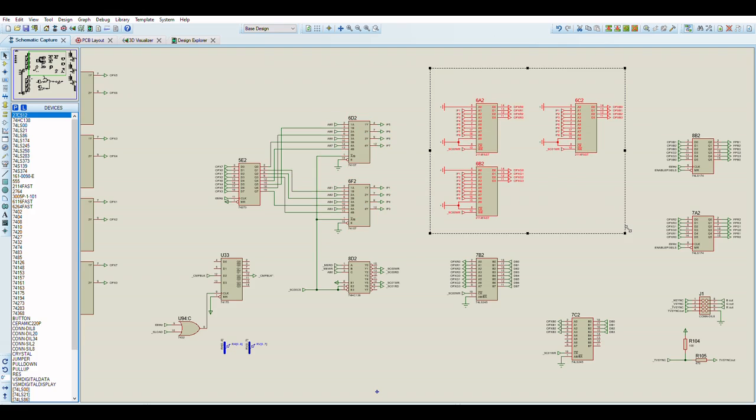These are 4-bit outputs, and there are 3 2114s, and these serve perfectly well to store and retrieve palette data. I saw no real value in changing this to a 6264, for example, because this allows 3 simultaneous reads of RGB data, 4 bits of RGB data.